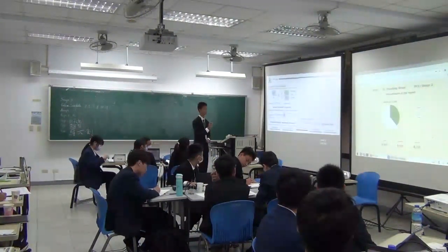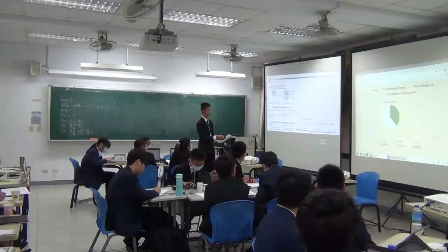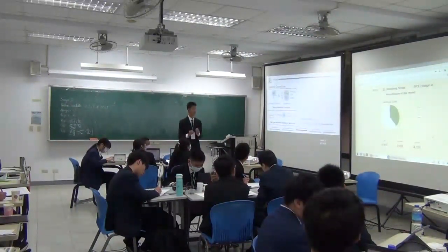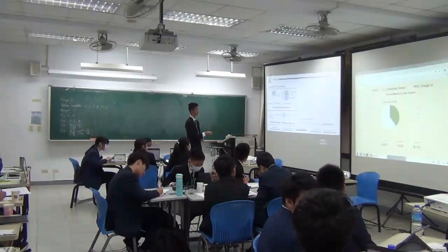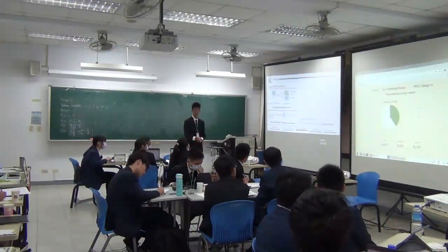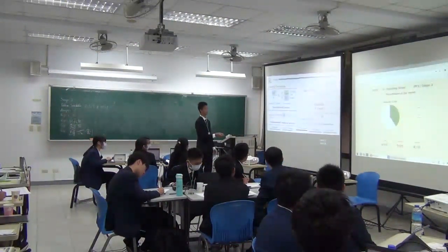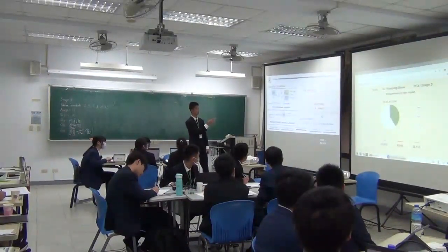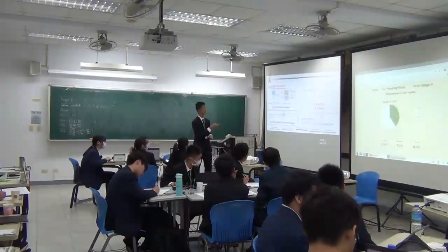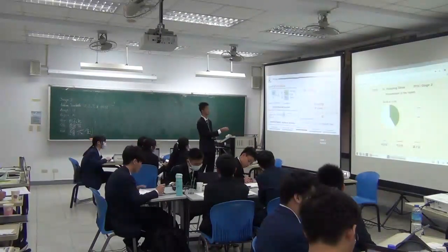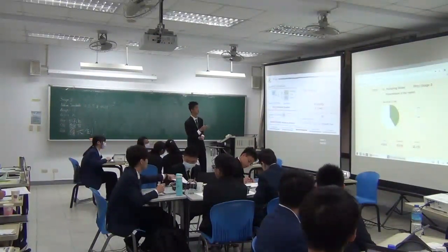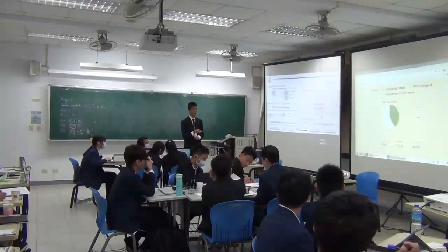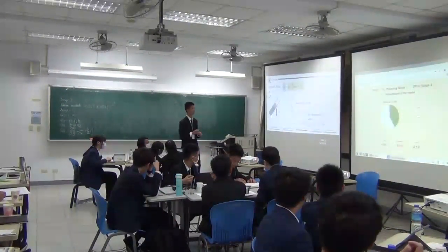Now, if we calculate the Reynolds number of our flow, we see that it is above 10,000, which means it's a turbulent flow. So we have to use this equation to find the coefficient Fd here. Now, you can take a look at this graph. The correction of viscosity will reduce the exit velocity. However, the difference is not significant. It's only to around 0.0005 meters per second, not very significant.